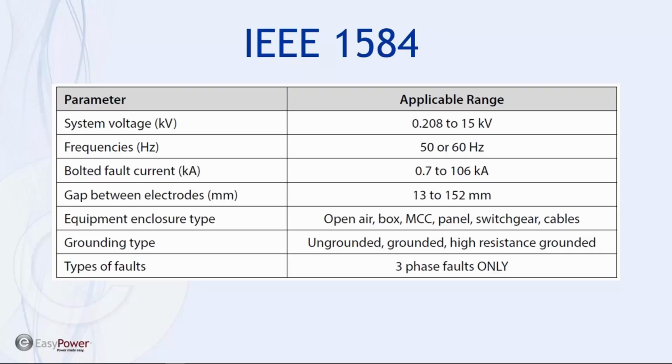The de facto recommended standard for most systems is the IEEE 1584 model, which was developed in 2002. That was developed by running a bunch of testing on actual arcing events, and then the model was developed by coming up with a best fit equation that met the empirical data.